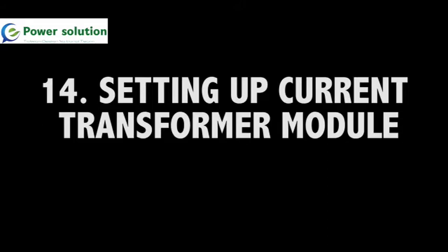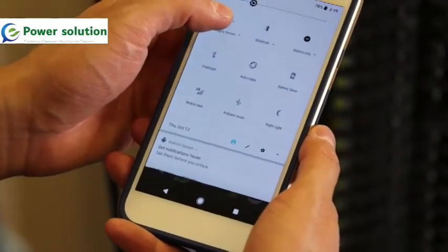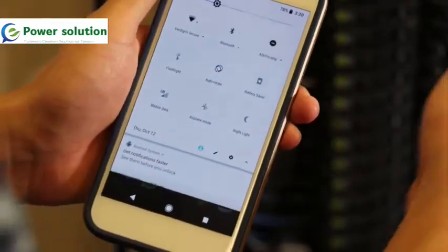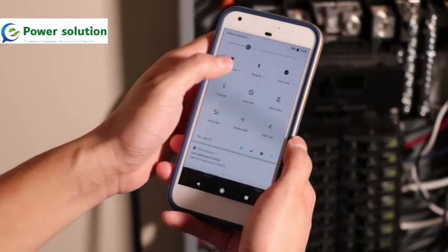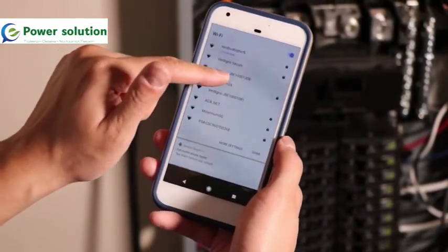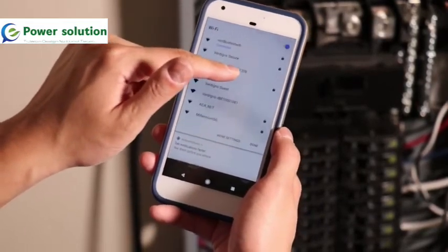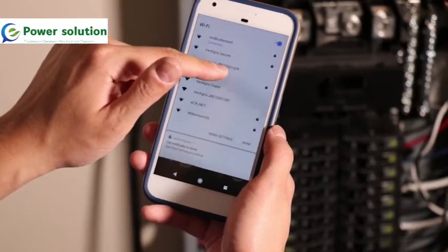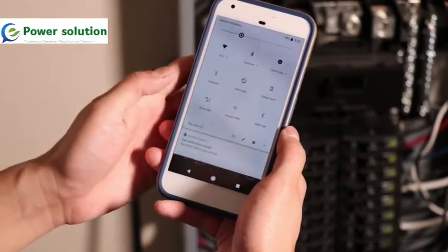The next stage of our process is that we will go through the commissioning process. Once your system is connected and powered on, it'll emit a wireless hotspot that you can connect to. Open any mobile device or laptop and look for a Wi-Fi network that says vertigo dash and the serial number of your system. In this case, we've installed system 10001308. I'm going to connect to that system.